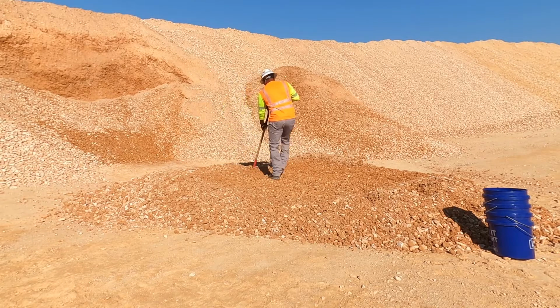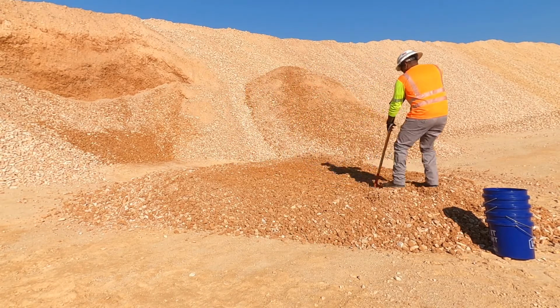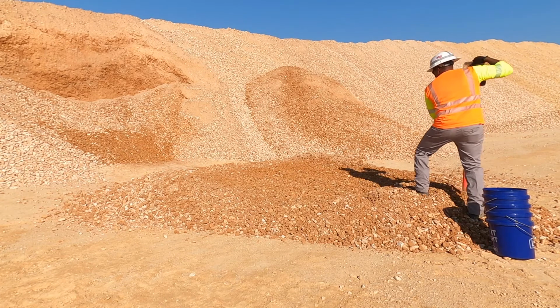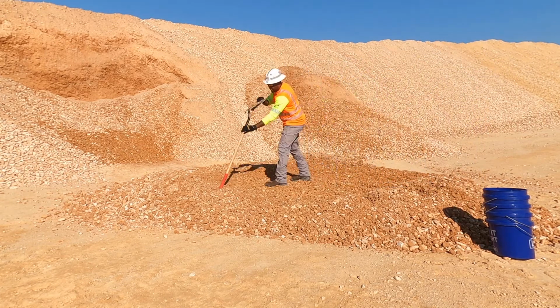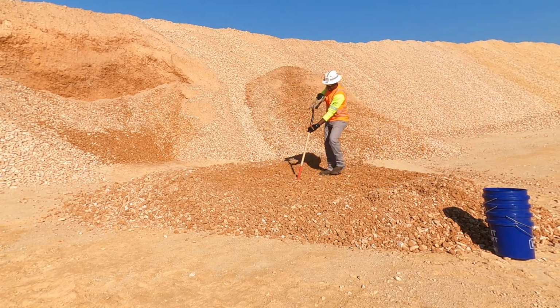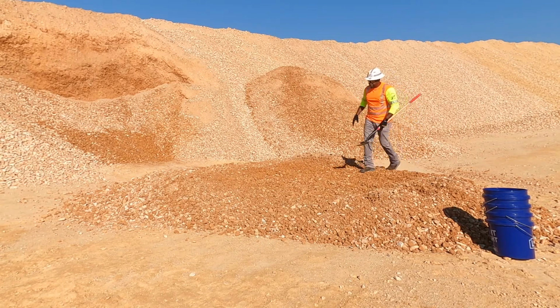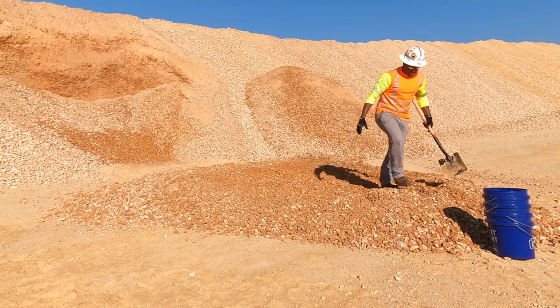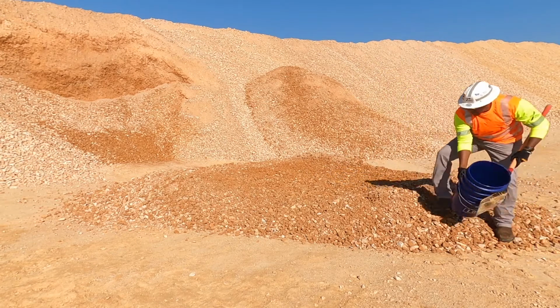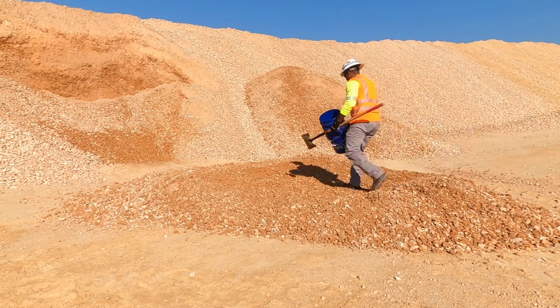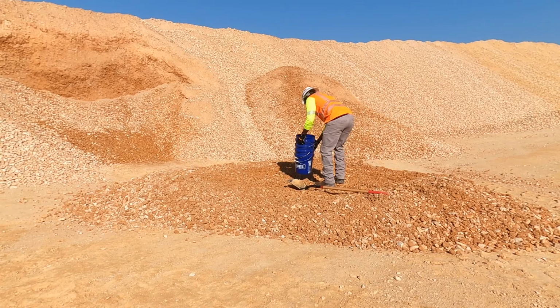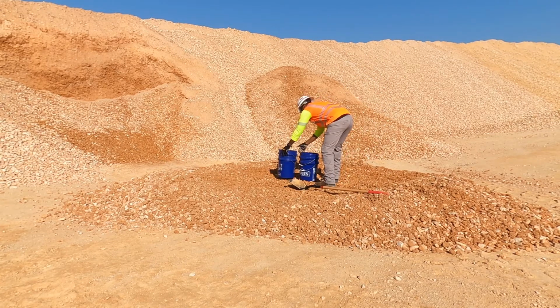Divide the sample pad into 4 quadrants and sample equal amounts of aggregate evenly across each quadrant. Place clean sample bags or containers near the center of the sampling pad and obtain the sample across the flat area staying more than 1 foot away from the edges.